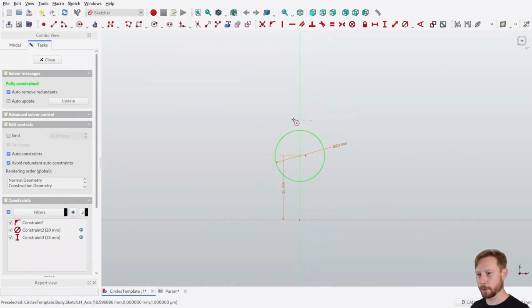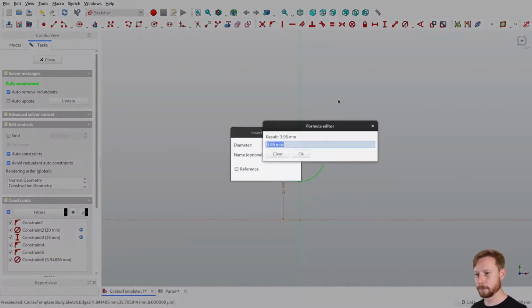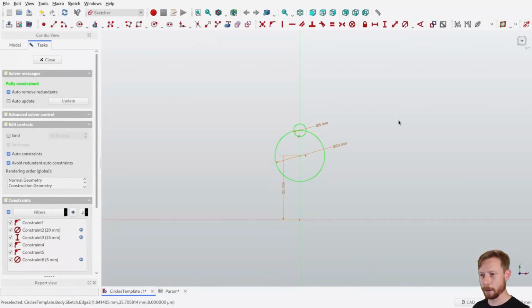And we'll throw in one more circle attached to the same center X line, and we'll also attach it to the outside of the larger circle. Give it a diameter from the spreadsheet as well. If I can type today. Okay, we've got a fully constrained sketch here. I can't drag anything around. FreeCAD's happy with it. Everything's fully defined.